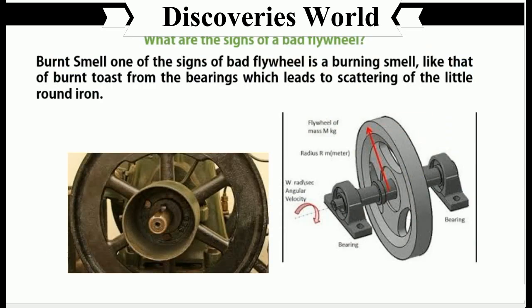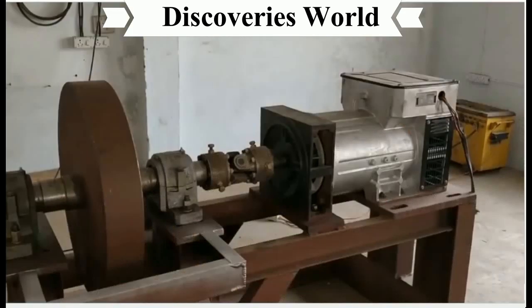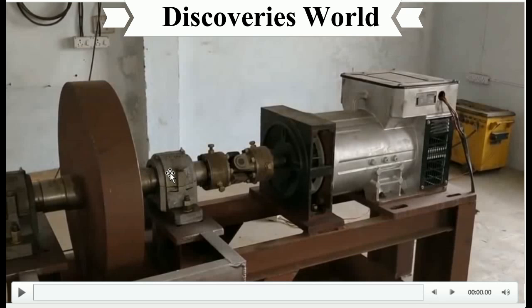Now, how do you know about a faulty flywheel system? There are different signs for you to know when a flywheel is faulty. One, you look at the bearing. This is the bearings. When the bearings crash, the flywheel cannot turn smoothly because most flywheels fit on bearings. Just like what you see here, there are bearings here, and there's a rod that connects this flywheel through the bearings to this generator.